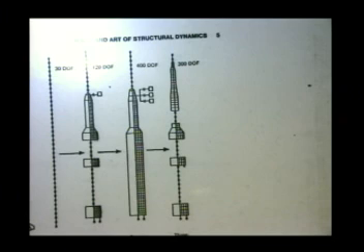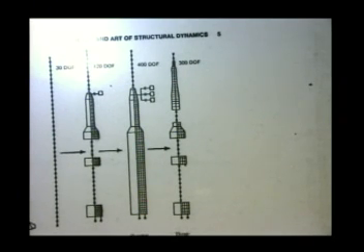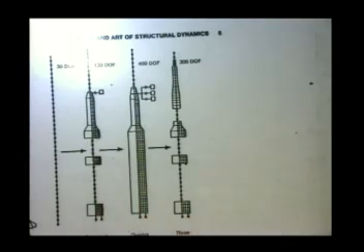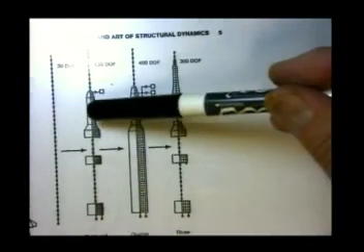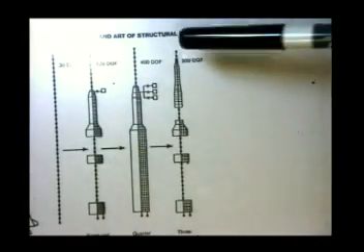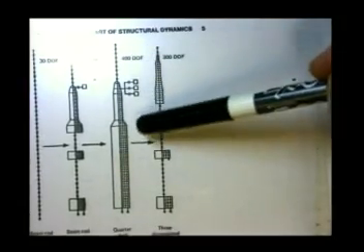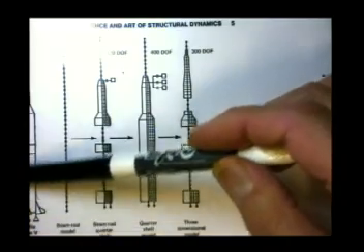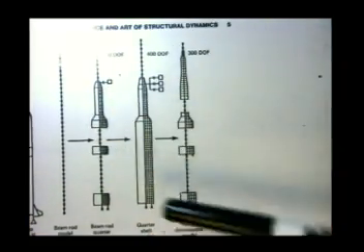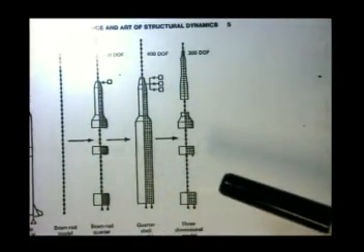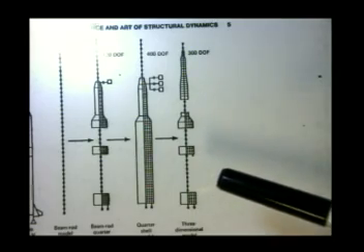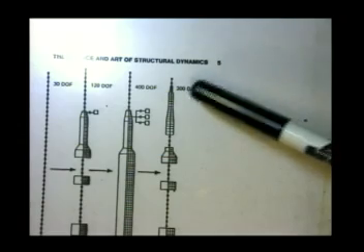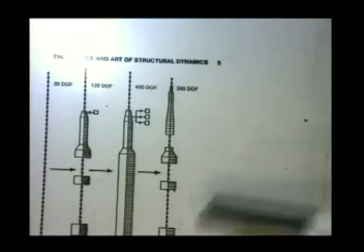Or if we want a better approximation, then it is, say, a 120 degrees of freedom system. We see a bit more details here and here. Then a 400 degrees of freedom system. Analysis is done only for the half part. Why? Because there is a symmetry, a rotationally symmetric system. Then a more difficult 3-dimensional model, that is a 300 degrees of freedom system, etc.